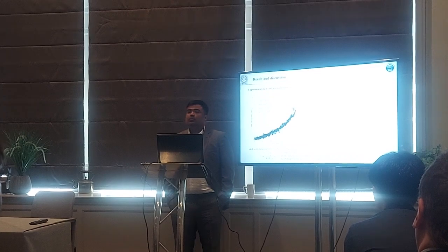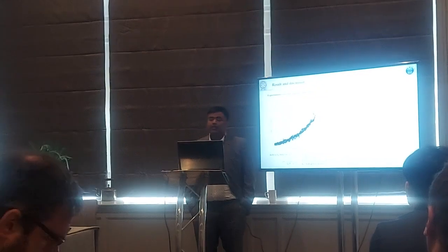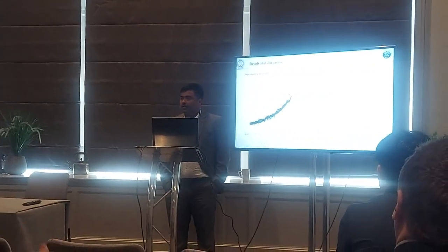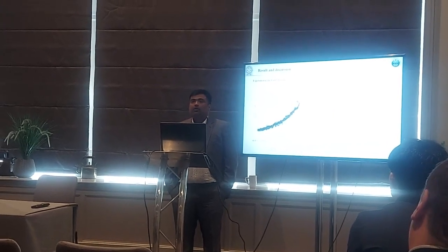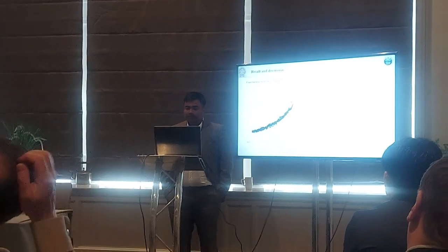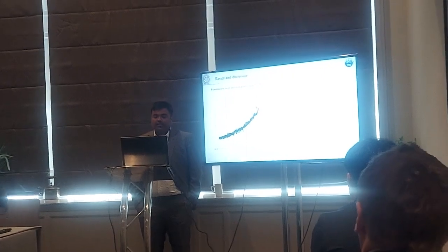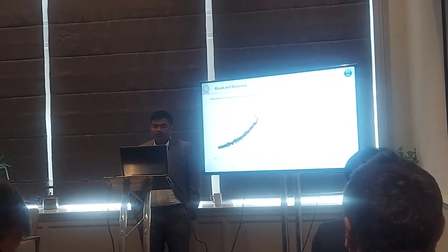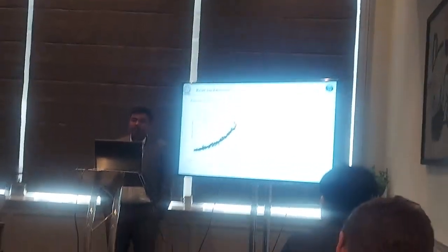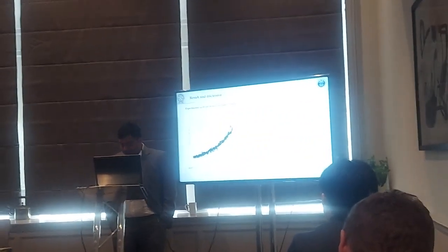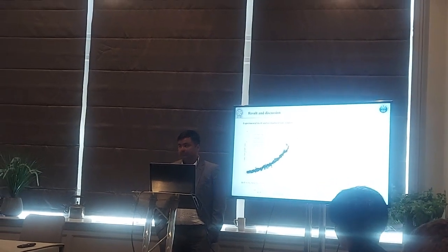So these are my results, and before discussing the results, I will tell you how I performed my test. I have used the ASTM E1457 standard, and as per the ASTM standard, I made the sample first. I used a CT sample, compact tension test, at a temperature of 650 degrees Celsius. At 650 degrees Celsius I tested different loads: 10 kN, 12 kN, 14 kN and 16 kN. To maintain the temperature I used K-type thermocouples, and for monitoring the crack growth I used the DCP.